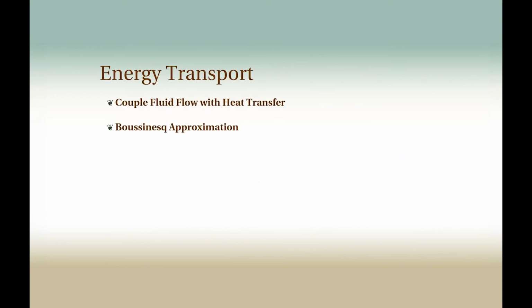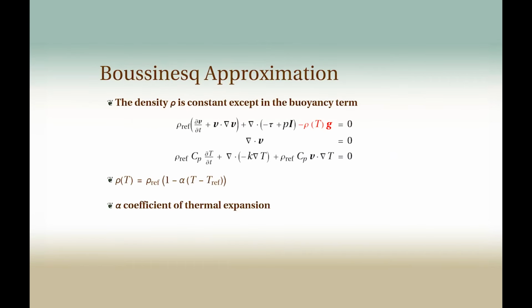Okay, we can also do energy transport. That means coupling fluid flow with heat transfer, and that's typically done via the Boussinesq approximation. So we have a coupling between a heat transfer equation and the fluid flow equation, and that coupling is done via this term, and that's the Boussinesq approximation. Again, theory is explained in the monograph.